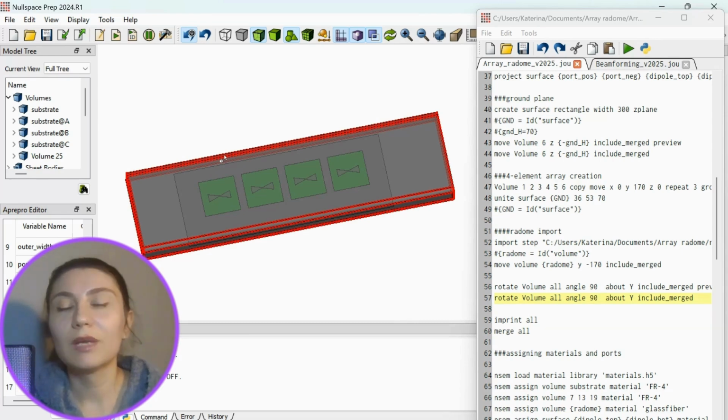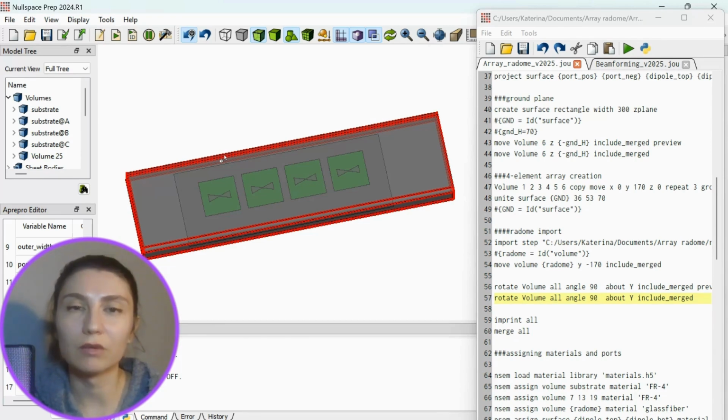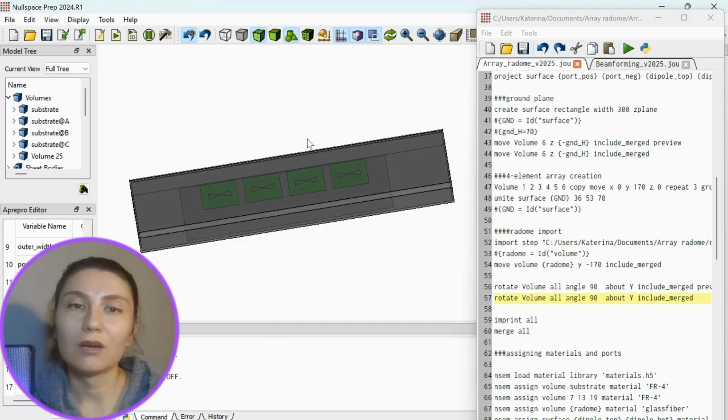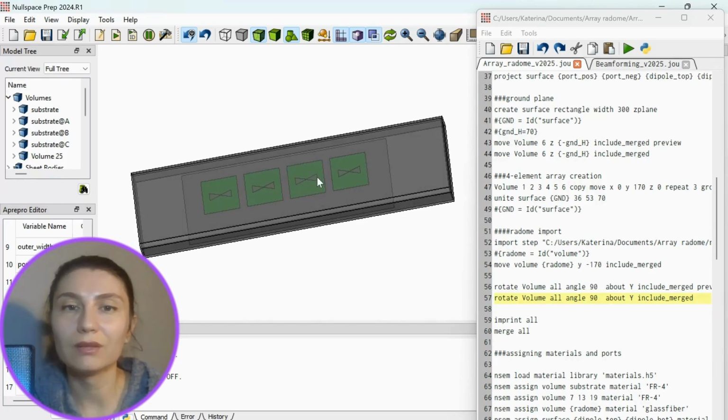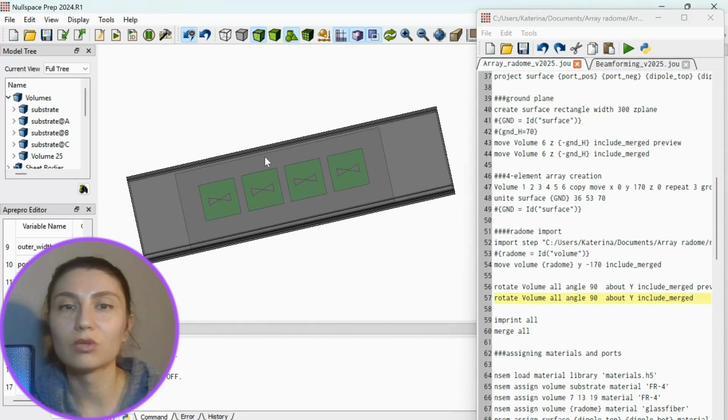Usually, maybe we try to not have these close antenna elements because we want to have some margin, for example for vibration tests and other mechanical inputs, so the antenna inside will not be damaged. But we also try to use the maximum amount of space inside the radome in all dimensions, in height, in width, and length. So this case, where the antenna element is close to the top of the radome, is not something unusual.